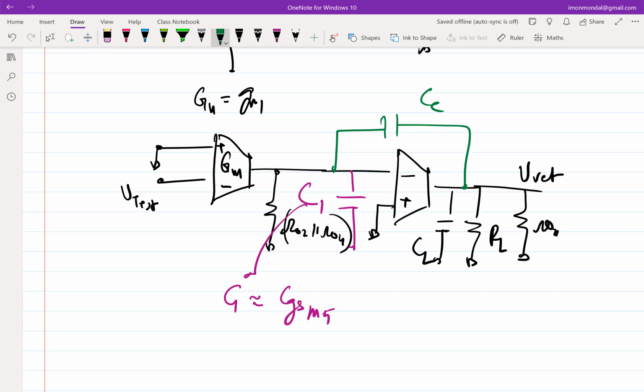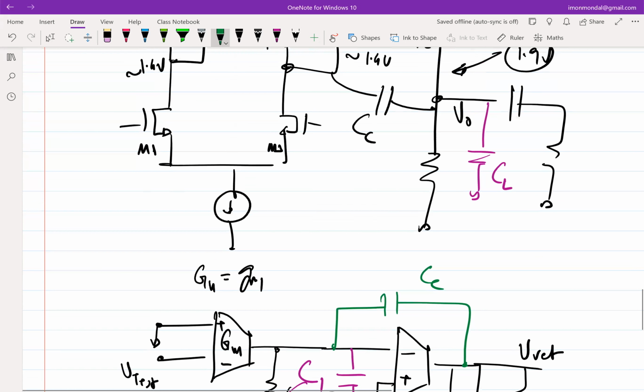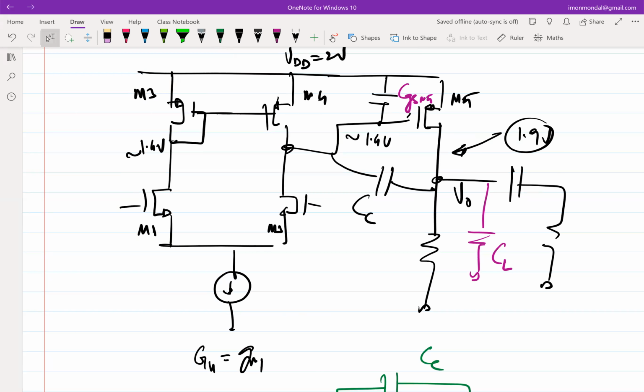And it will be even more relevant because now in this case, I used a resistance. You need not use a resistance. You can use a current source, right? I can use a current source here, and the current source is nothing but another transistor. So this is also a transistor. And there is probably a master current source.